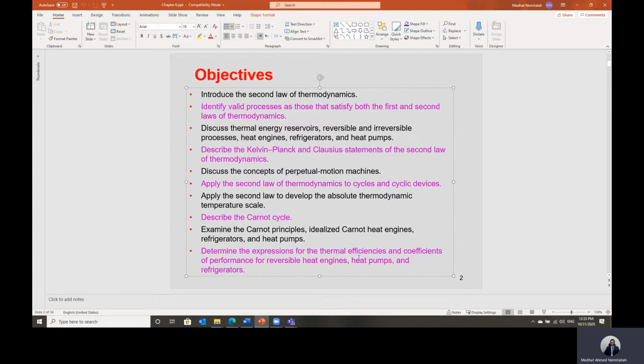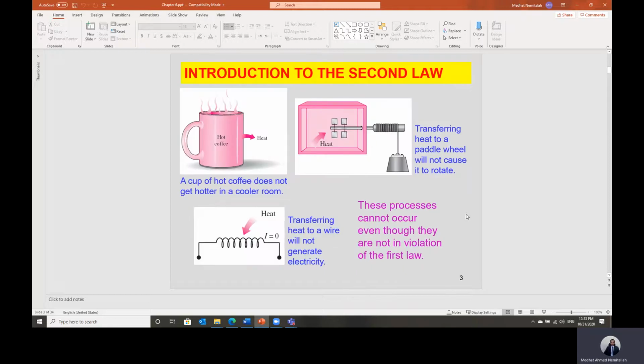to calculate the efficiency of heat engine. And for refrigeration, heat pump and air conditioning cycles, we don't evaluate the performance using efficiency. We evaluate the performance of those systems using what we call the coefficient of performance. So efficiency is applied for heat engine, and coefficient of performance is the parameter to evaluate the performance of refrigeration and heat pump systems. We'll see all of this, how we can calculate the efficiency and the coefficient of performance.